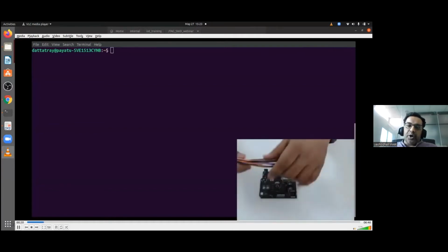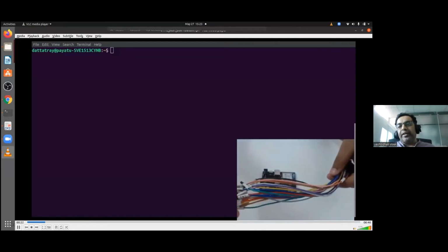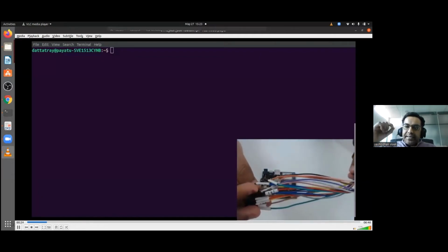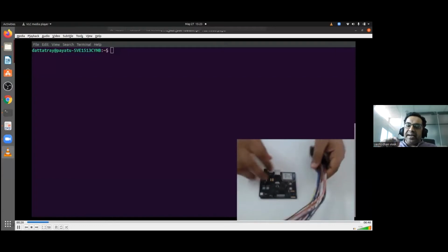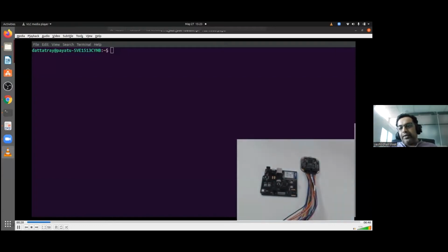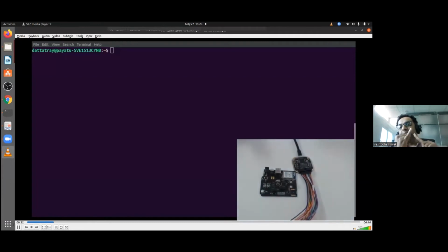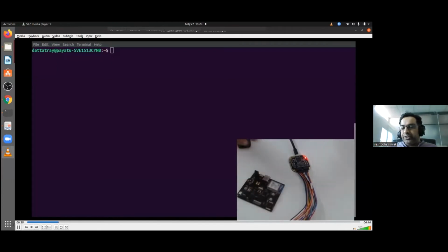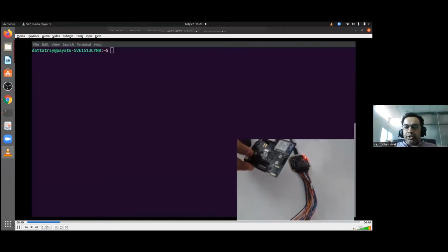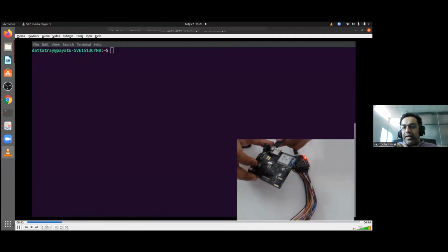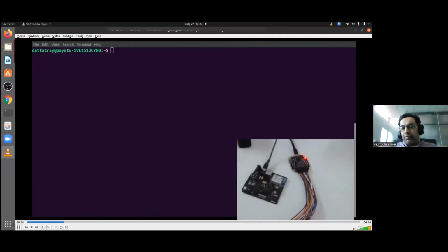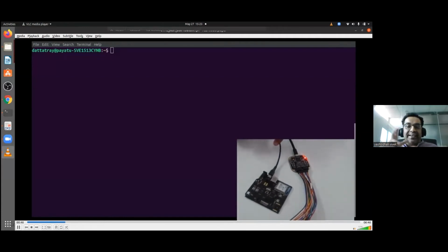Now, this is our EXPLIoT bus auditor. The job of the EXPLIoT bus auditor is to scan all the pins and tell which pin is what. Meaning, it will tell which pin is TRST, which pin is TCK, which pin is TMS, which is TDI, TDO. Right? The only thing we need is to identify the common ground, which is very easy. So first of all, we'll connect the ground, and after powering, the debug board and the EXPLIoT have been powered up.